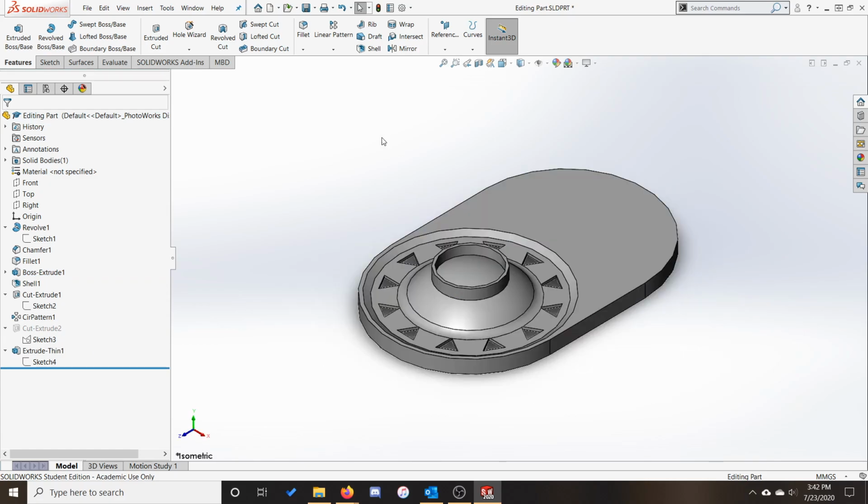Magnificent. Well, with that, we turned our original object into what could charitably be described as a hat, and maybe we learned something along the way. With SolidWorks, you can edit sketches, features, sketch planes, feature ordering, control feature suppression, and even add new features to earlier points in the design tree. The editing process takes practice, but SolidWorks has plenty of tools that can help you change your models.